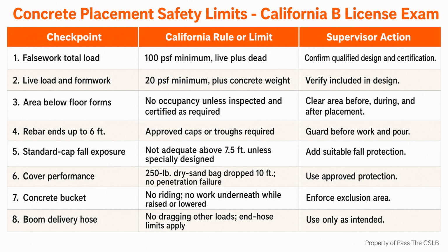I want to pause on the cap rule because it is easy to oversimplify. A cap that helps with a same-level trip hazard is not automatically a fall arrest system. Fall height changes impact energy. California safety orders draw a specific line at 7 1/2 feet for standard caps. Above that exposure, the site needs a specially designed protection system or separate fall protection appropriate to the work.